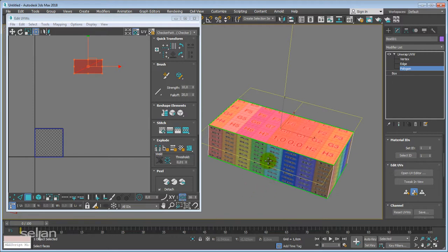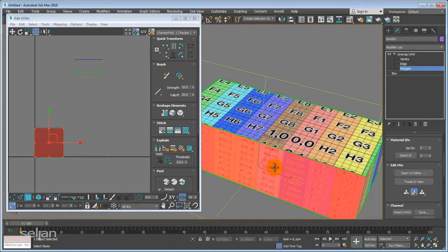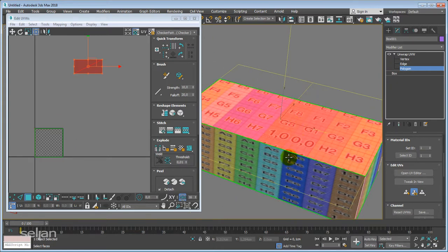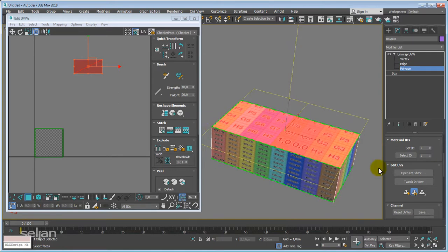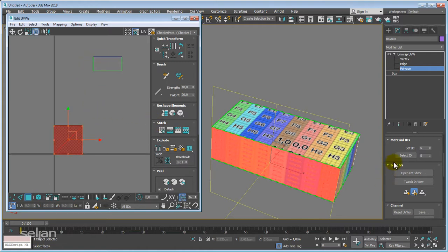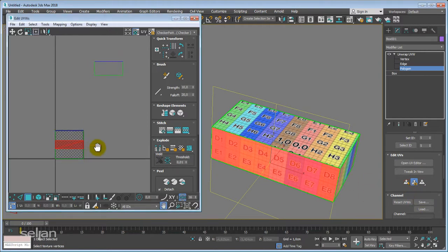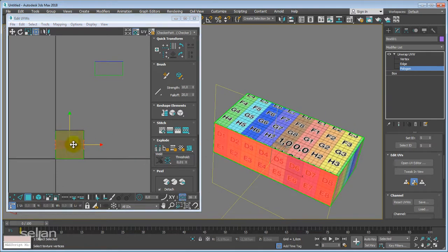Now to move on, this will be my next choice. So this face will be connected in the end. It will be connected with this one by using a welding method. So I will weld these two elements, but just in a slow pace. Okay, now the method is pretty much simple. I will use again the automatic quick planar map because it's a single simple map. Wow, cool. Now, grabbing, moving it away.